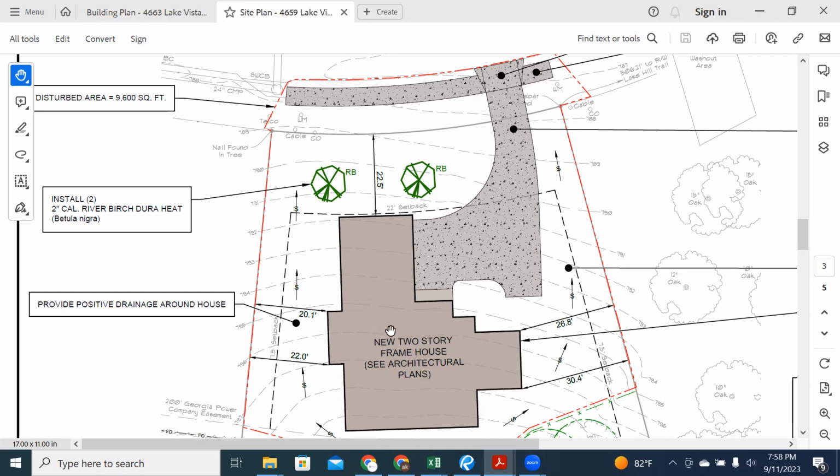So normally we have to put a pump truck on this side right here. When the concrete truck pours the concrete into its chute, the pump truck then shoots it out and fills out the footings and the slabs.